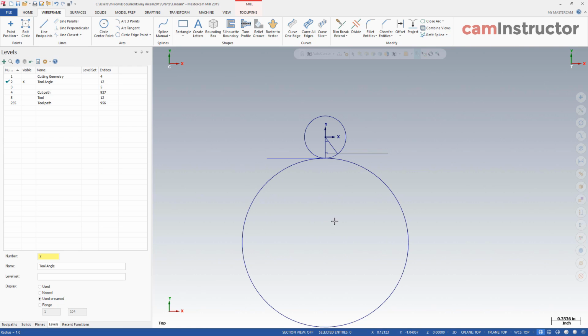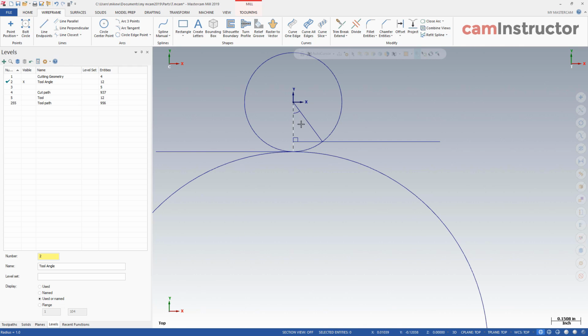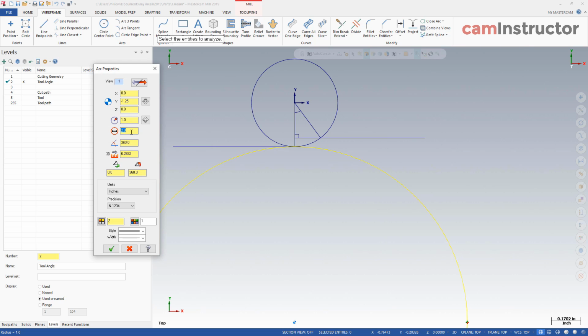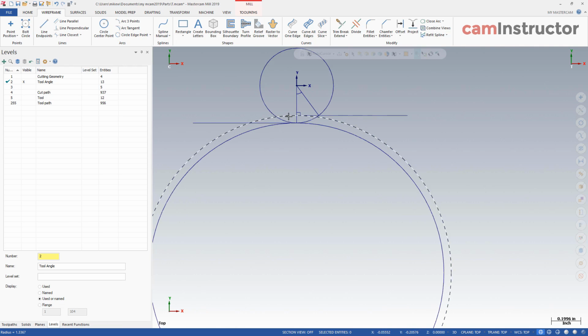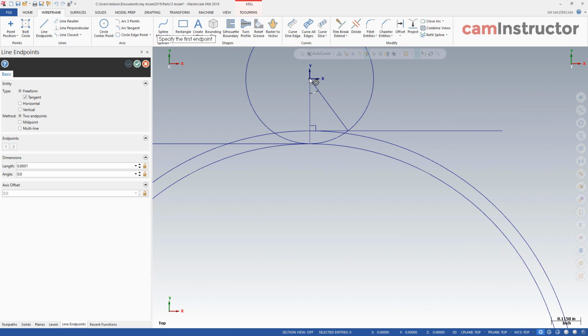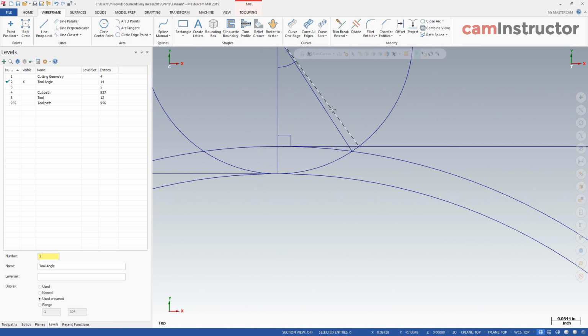So with this circle, we said that this tool, we needed to do a 50 thou step over to maintain this cutter engagement. So if this is what we want to cut, this is a 2-inch diameter circle. So for a 50 thou cut depth, we need to draw a cut path that is at 2.1, a 2.1 diameter circle. Okay, so notice what happens out here. The cutter is actually only engaged up to this point. So the angle of engagement here is much less.